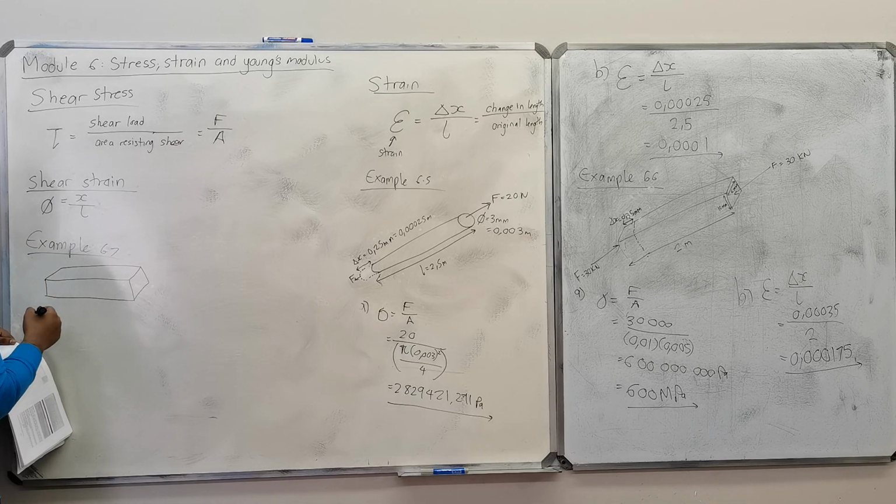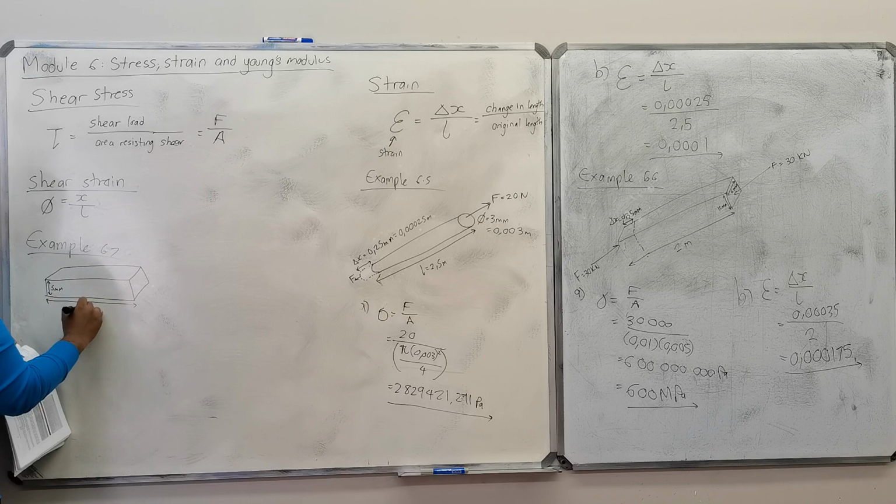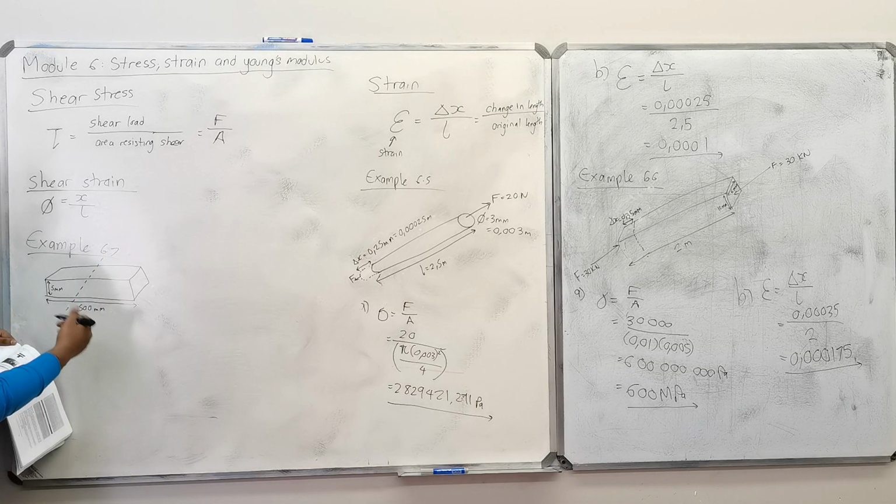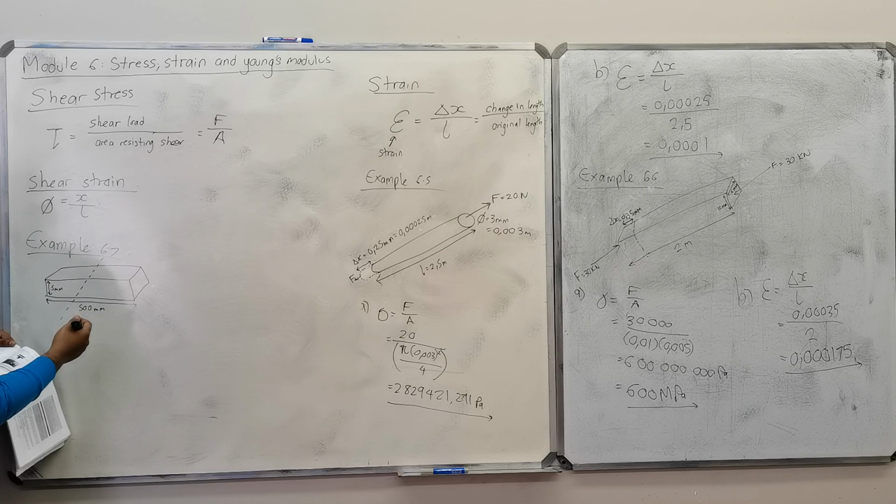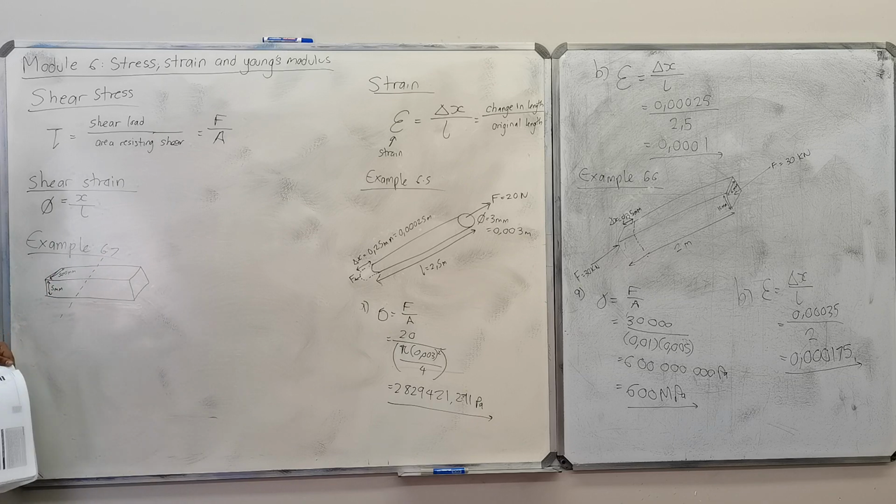Pretend that it's a page, a very thick sheet. It's 5 millimeters thick and 500 millimeters wide. It's cut by a guillotine. A guillotine basically cuts it like that, right? They don't keep cutting that. The 500 mil is the side, this is the length. This here is 500. Calculate the force that is needed if the ultimate shear stress is 60 MPa.